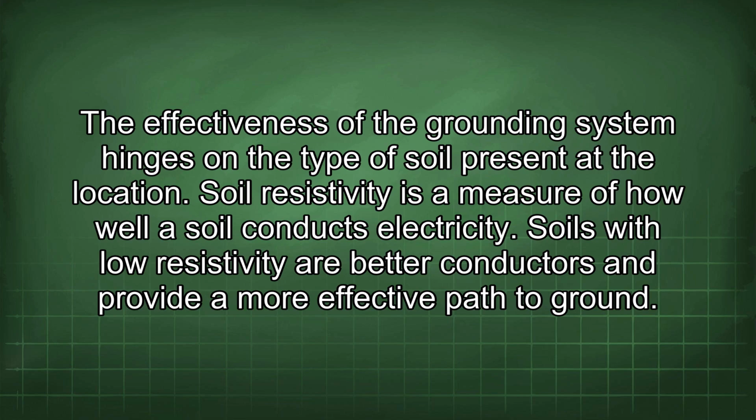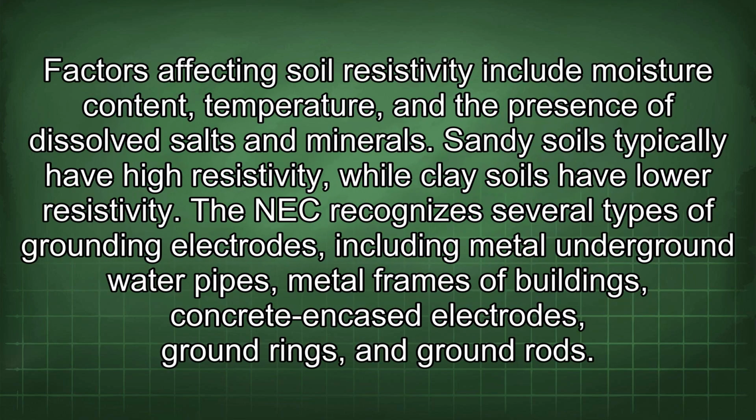Soil resistivity is a measure of how well a soil conducts electricity. Soils with low resistivity are better conductors and provide a more effective path to ground. Factors affecting soil resistivity include moisture content, temperature, and the presence of dissolved salts and minerals. Sandy soils typically have high resistivity, while clay soils have lower resistivity.